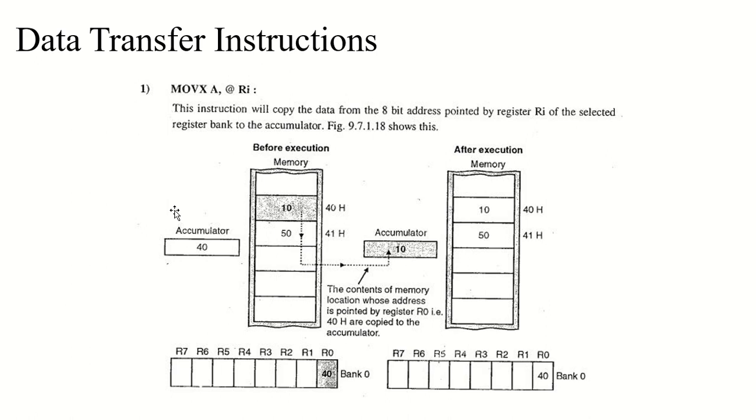Byte of external data memory, that is why we are adding this x after move. And depending on whether the indirect address provided to the external data RAM is 8-bit or 16-bit, there are two types of instruction. In the first type, content of register R0 and R1 of current register bank provide 8-bit address that is multiplexed with the data on port 0, and 8 bits are sufficient for external input output decoding, or for a relatively small RAM array.